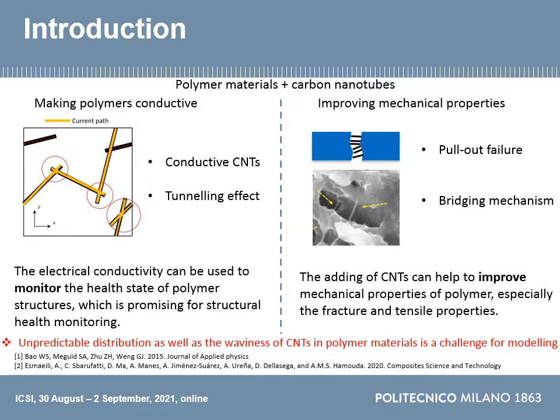But if we want to further investigate this kind of nanocomposites, the unpredictable distribution, the waviness, or the unpredictable positions of the CNTs inside the polymer materials will be a headache. It is a challenge for the modeling process, and it's also really hard to measure during experiments without cutting the sample.